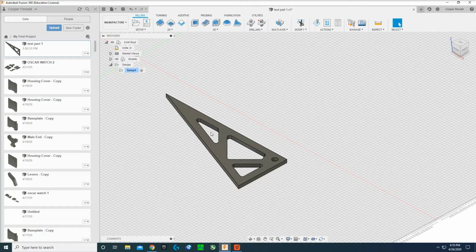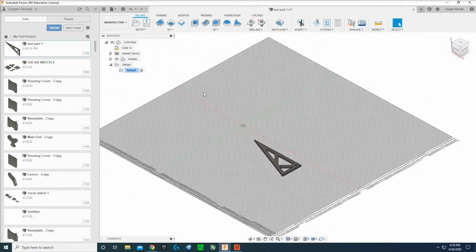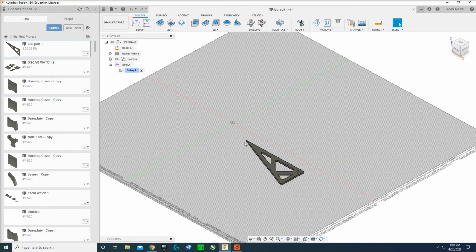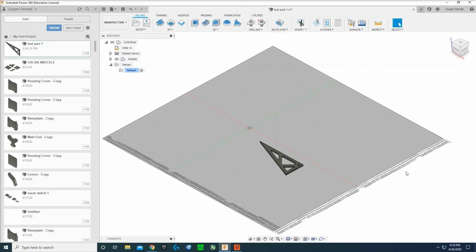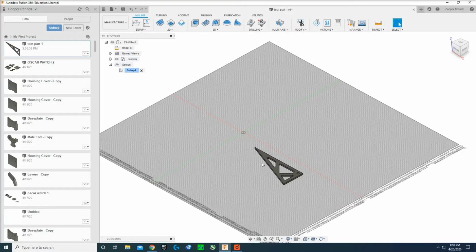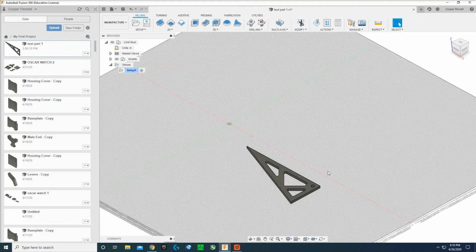Because the way it works, like the model shows right here, you've got a huge sheet of aluminum. If you cut out the border of the part, this whole part is going to be separate from the rest of the stock, which is secured to the table, and the part's just going to come up, right? Because if this whole gray box right here is the stock material, I might only be drilling in 4 bolts or 4 screws in these 4 corners, and not in the actual part. So if you machine the edge of the part, it's just going to come free, and that's not good. So always machine the edge of the part last.